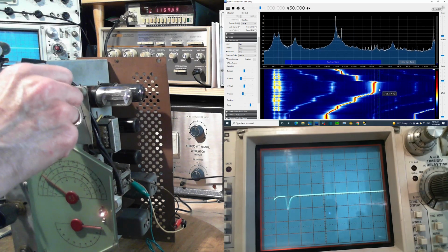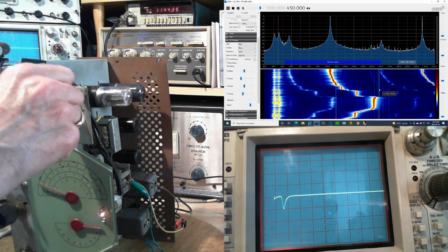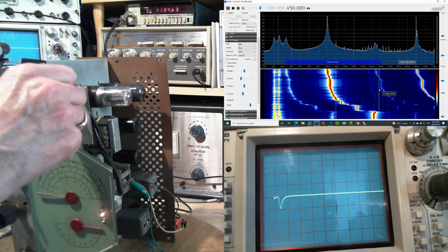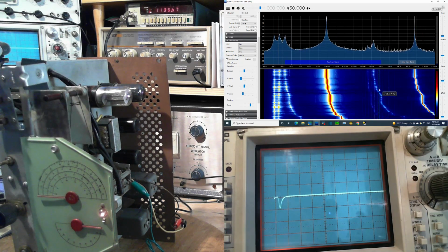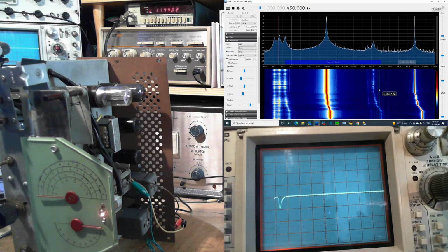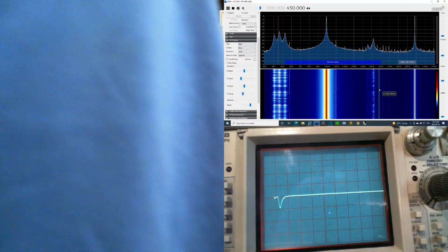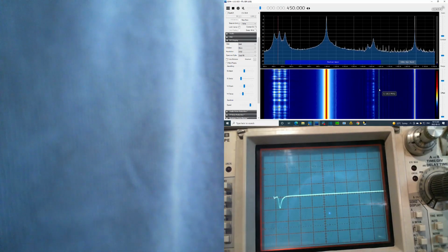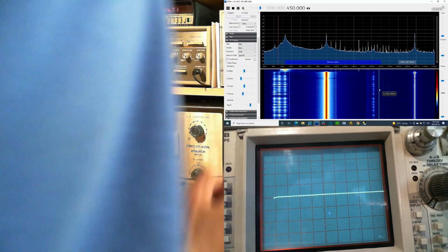So the 3 peaks. Looking in the IF now, there are 3 peaks sitting there. The one to the right is the front end tuning of the radio, and the sweep is causing that. The other 2 are being caused by conversion. Let's get rid of the local oscillator.